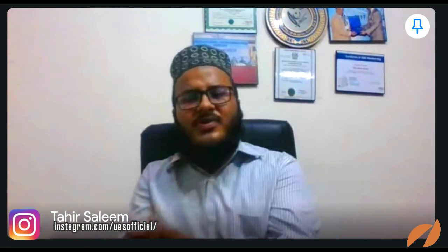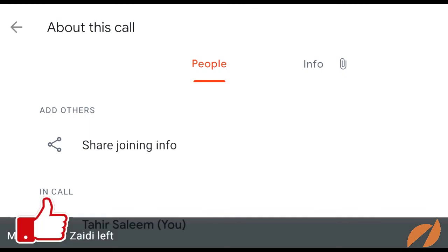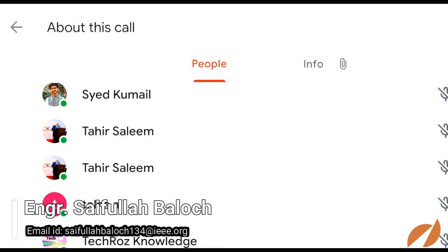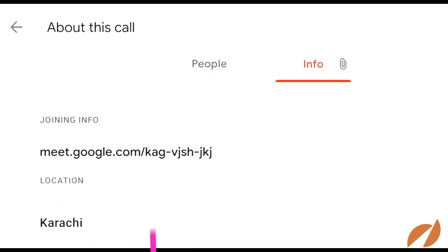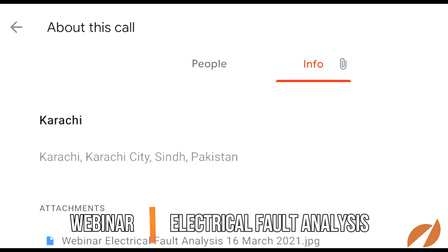You have to assume that the fault is occurring on bus 1 or bus 2 or at a motor circuit or generator circuit, whatever. Our experience is that the utility companies, even the industrial sector, are selecting the wrong components, not as per their fault levels. So you have to assume faults at different places in your system and put your components accordingly, so that your safety compliance will be done. Then you will be able to select your components accordingly.